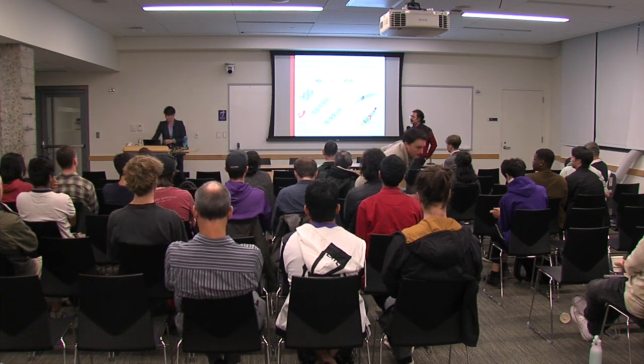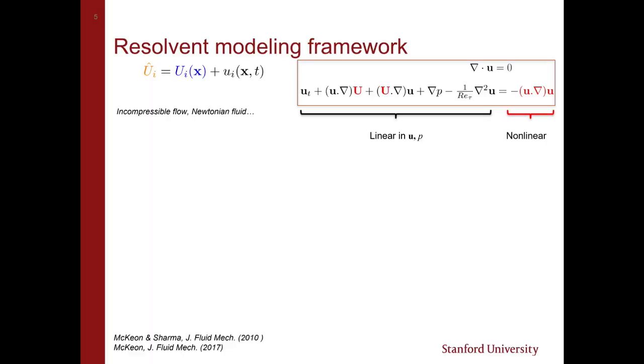So there are many things that you can do there, and I did not describe them all. And there are people doing very creative things in that space. Let's go to this one. Right, so everything I've showed you kept the full nonlinear forcing over here and just the turbulent mean over here. In the limit, right, if you think about an eddy viscosity type forcing, I could write this as a function of linear, the left variables on the left-hand side.